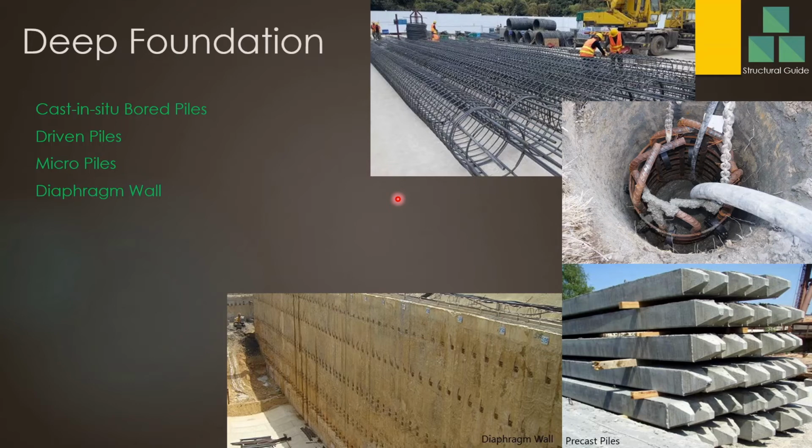Mostly cast-in-situ bored piles continue up to the rock, and then beyond the rock we continue a depth called the socketing depth.